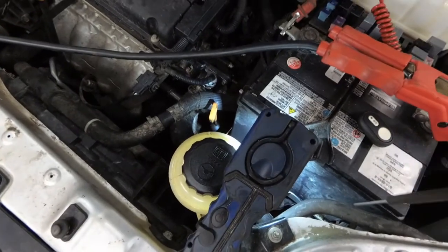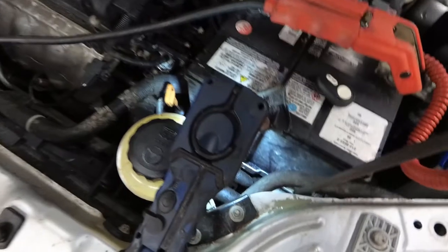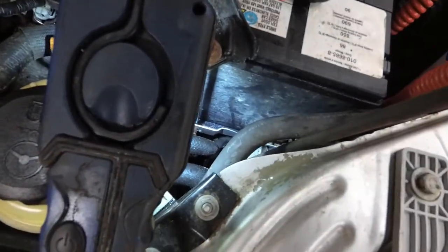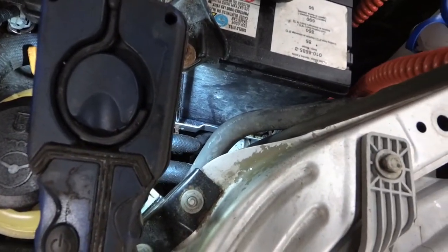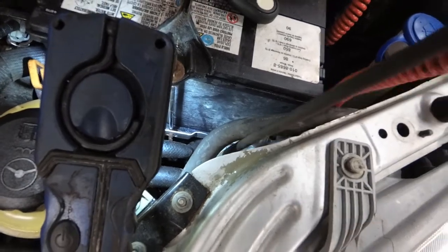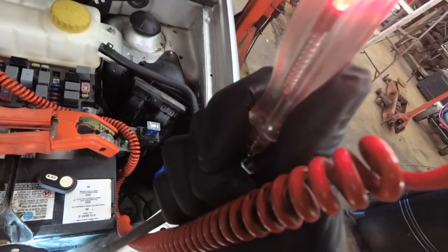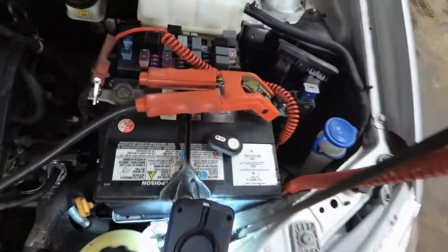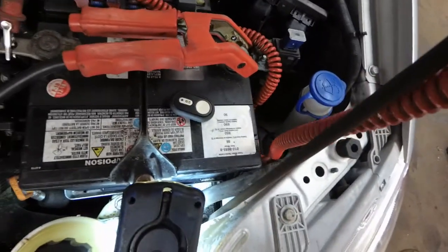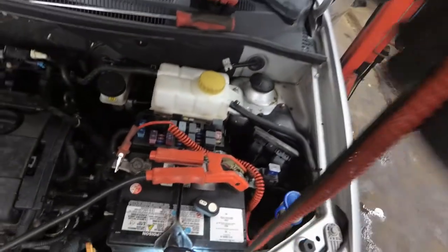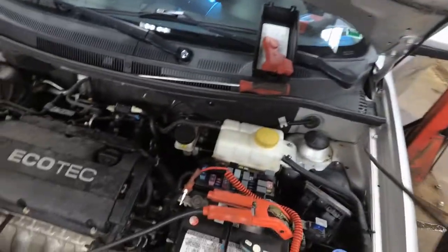So I've got the scan tool commanding the relay on, and I've got a long test probe that I can put down here onto that terminal, and it's insulated so that it doesn't short. Let me get the light in here. Oh, I missed it. There we go. You can see there's power on that side of the resistor, but if I go over to the other side of the resistor, no power. So that dropping resistor has failed.